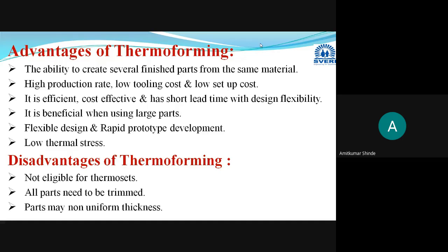Here we can give any kind of shape and size. By changing your mold design, you can change the shape of the product. You can also apply this process to obtain larger sized products. There are flexible designs too. Whenever you are making a prototype of any component before manufacturing it, an exact replica of the final product is made with the help of this thermoforming process only.